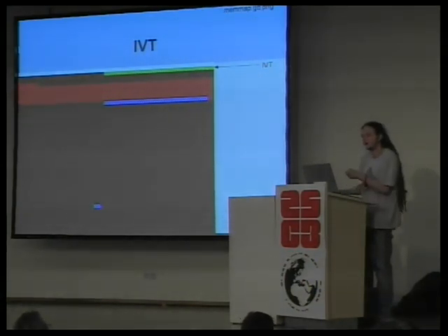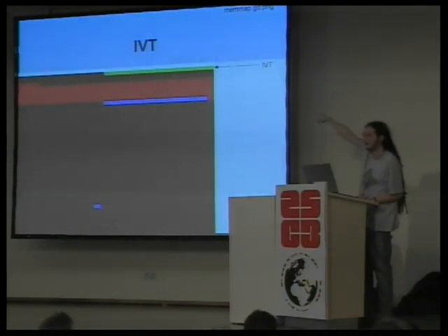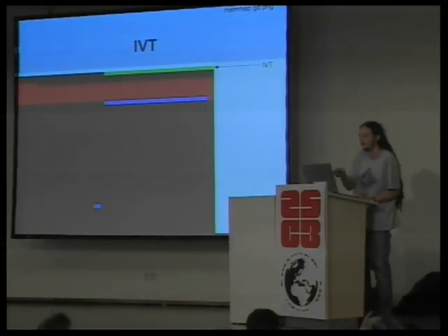And that's the reset vector of the lower image. So while FFFE is used at the top to begin the bootloader, F7FE in the lower bootloader is ignored. Instead, the value is hard-coded elsewhere within the red image.